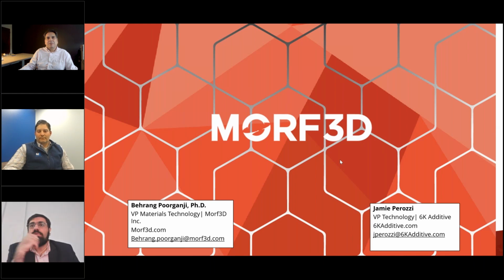If, for example, we go through MMPDS terminology, you can say I have the S basis level, or now with the additive, C basis, D basis level, and these are different lots of powder in different machines, and you have to build 30 coupons or 100 coupons or 300 coupons. It really depends, but here we basically look at and say that, okay, we need to have some minimum tensile size, a minimum fatigue, the number of coupons to be tested.